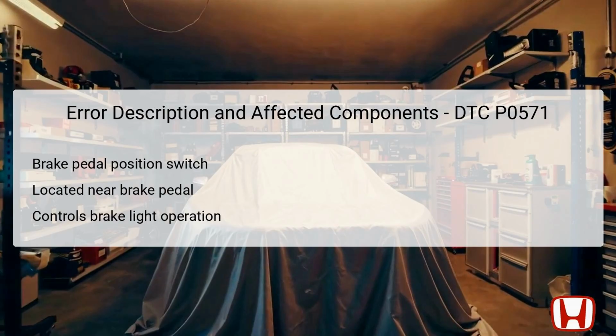Additionally, the switch impacts the cruise control system, ensuring that it disengages when the brakes are applied for safety. Issues with this switch can hinder normal braking function and create confusion for drivers and other road users. Regular inspection and maintenance of the brake pedal position switch are critical for overall vehicle safety.